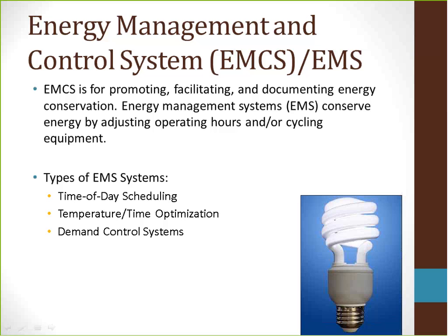The next is temperature and time optimizations. These systems provide for the control of multiple functions and more sophisticated control of temperature, setback, and set forwards. Inside and outside air temperature are monitored and used accordingly to vary the time of startup or setback of heating